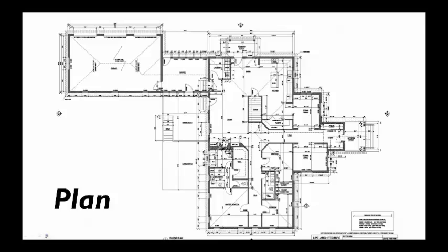And so it's like you're looking at that horizontal cut through the building, you're looking back down at the floor, and then everything that you see cut through, that's when you start to show hatched or more heavily shaded lines for walls. Anything that gets cut through there is a heavier or darker line weight. And if you squint your eyes, you can see where those walls are, because those are the ones that are more heavily shaded.